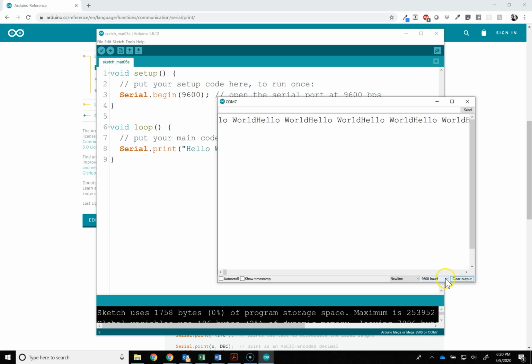One thing you'll notice is that the baud rate here needs to match the baud rate you use in your code. You can also use faster baud rates, so you can go super fast. However, 9600 is a really good one, and there's generally not a lot of justification for changing it. I'd recommend you just start at 9600, and if you have issues with communication, then maybe consider changing it. There are not a lot of cases in our class that would require that.